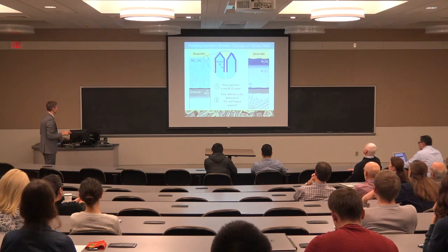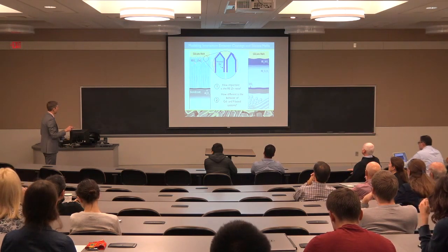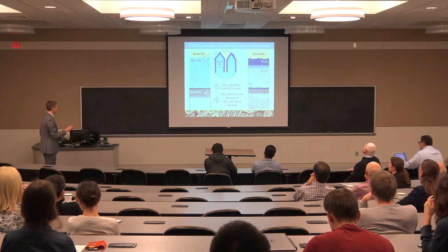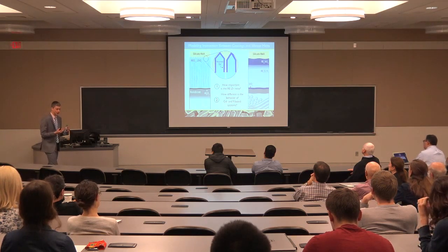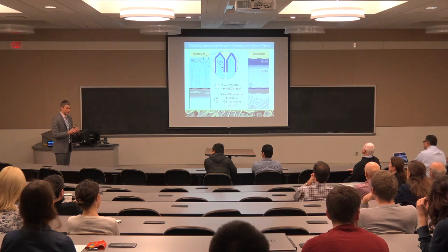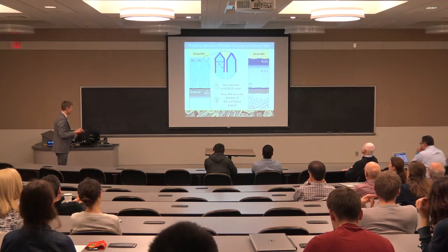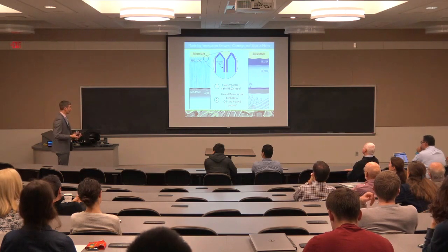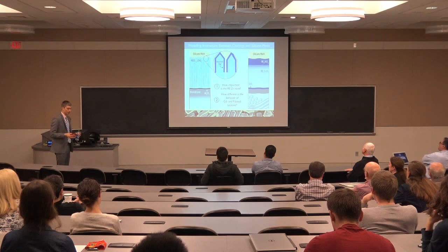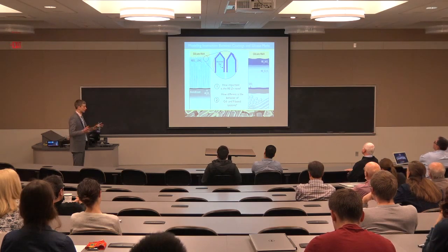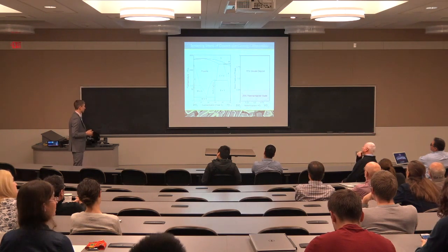So I'll also share a brief case study looking at this other problem, where our goal in the case of the segmented thermal barrier coatings is to limit the amount of penetration that we get into the coating. We want to maximize the amount of material that's crystallized for each mole of coating that dissolves into the system. And we'll ask similar questions about the role of melt composition, as well as try to make a comparison between, in this case, the gadolinium and the yttria-based systems in the context of the broader range of deposit compositions.